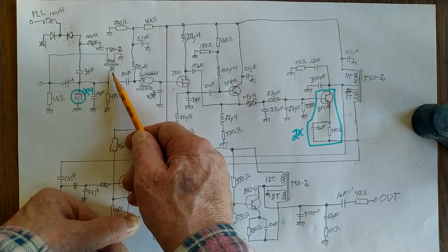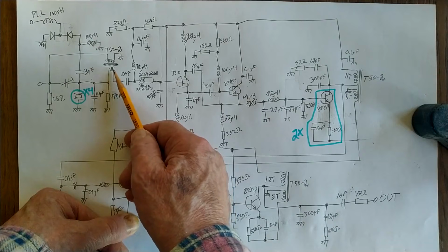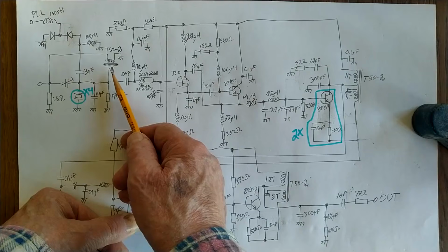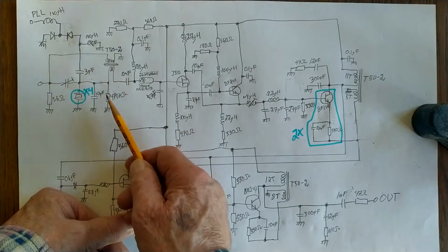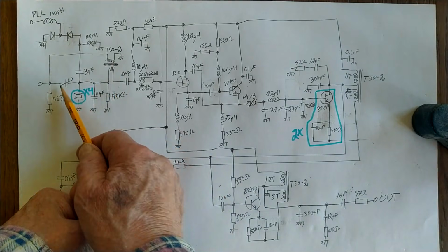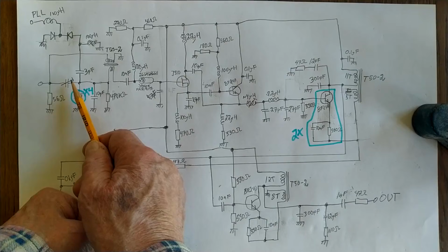So the first step is to set the number of turns to get something in the neighborhood of the right number ratio. And then one can fine-tune with this capacitor for a perfect symmetric response and very good suppression outside the frequency of resonance.